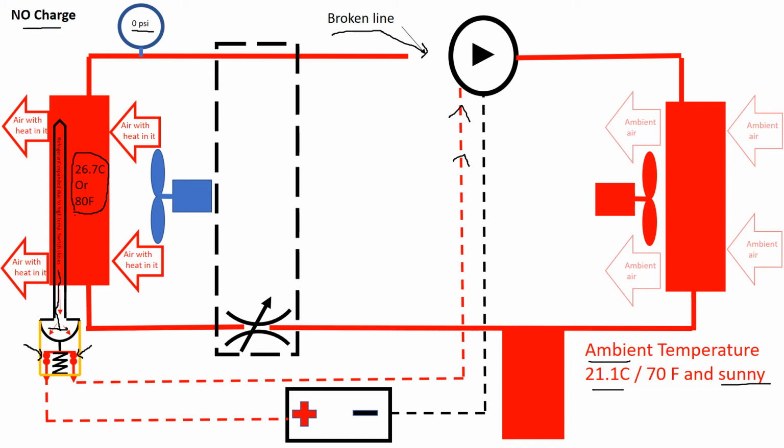Now this would be a very, very bad thing because especially with a hose broken, what we've got here is dirt, water vapor and whatever other contaminants are around are going to get drawn into that compressor and are going to destroy it from contamination.